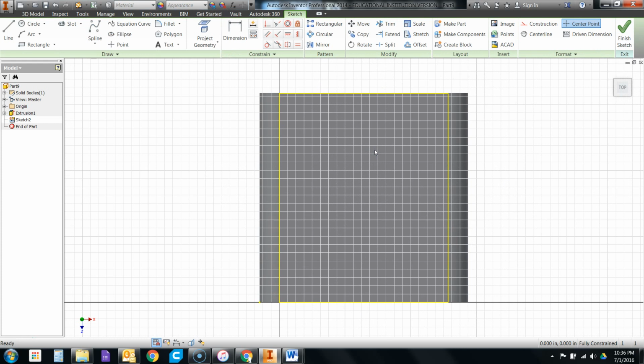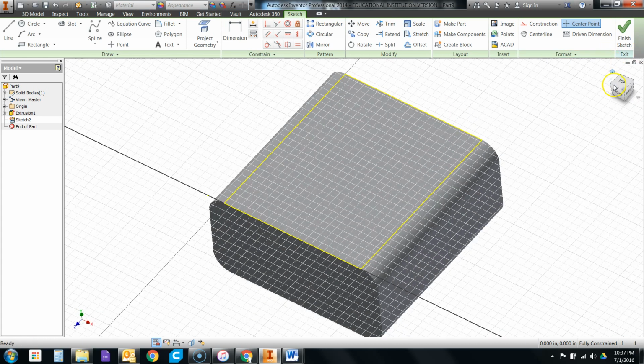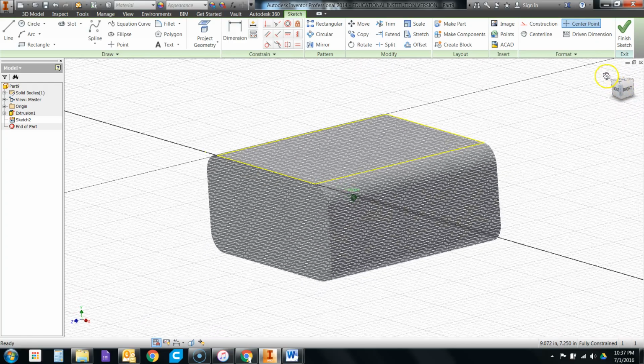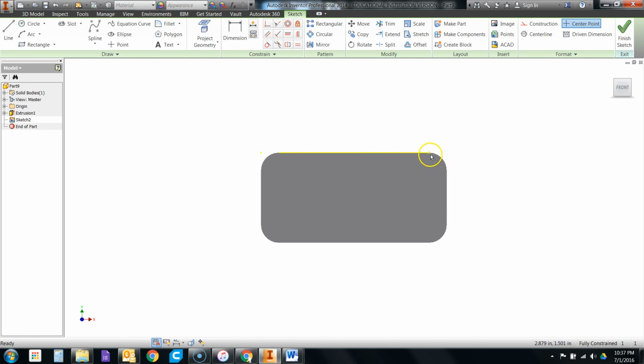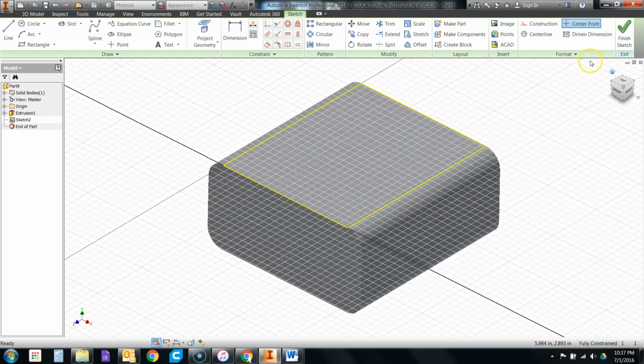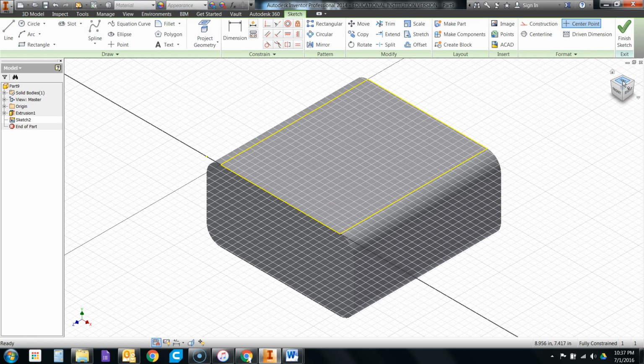Once this sketch is created, it automatically picks up any edges that are touching the sketch. And right now, those edges would be the top, right, front, back, and left edge. Notice that because this is curved, we only see this front edge as being right here. We don't pick up this curve on the top because it curves in the width and height direction, 2 dimensions that are only on the front and back faces. So, the top face now has this sketch on it.